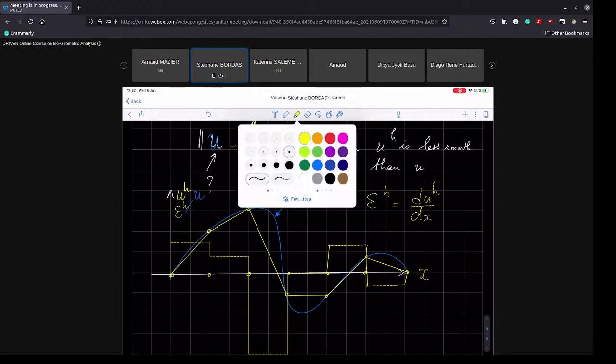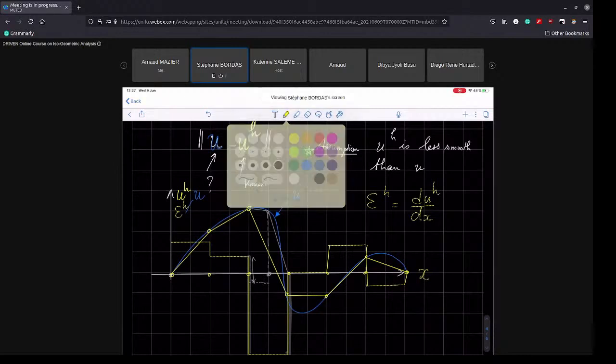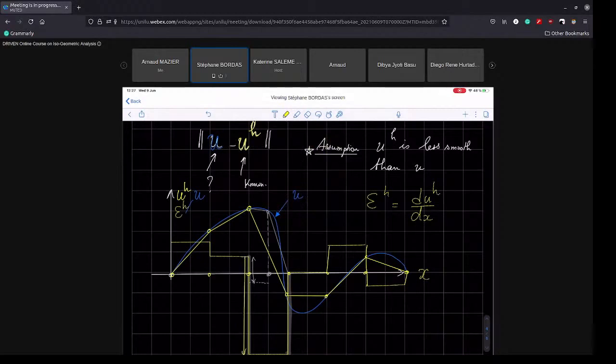Very simple. So you measure this and you say, oh, this is big. You measure this, oh, this is big. Therefore, in the next refinement step, I'm going to add a node here in the middle. And let's assume that we do this. So we go there, we look at the curve, which we don't know, and we compute, and we say, okay, well, now the jump is a little less. Okay, so, you know, I have a negative slope here, but it's quite small. So my new jump is this jump. And this jump is much less than the original jump, which was that jump, right? So now I have a smaller jump. And that smaller jump is good for me because it means that the error will be less.